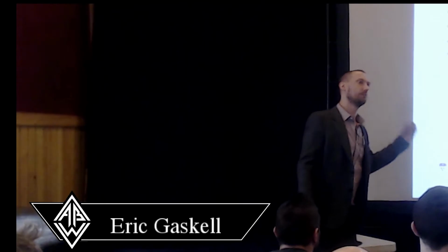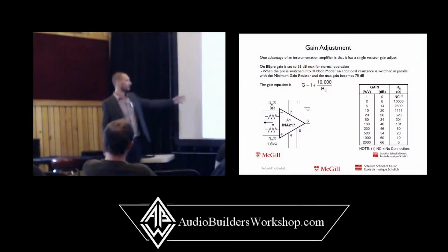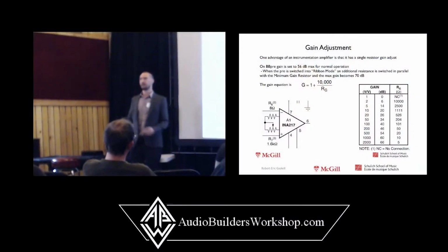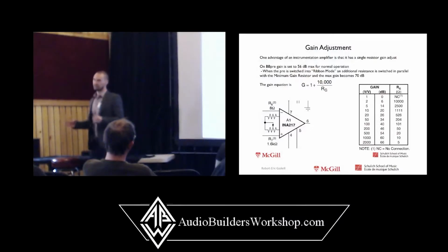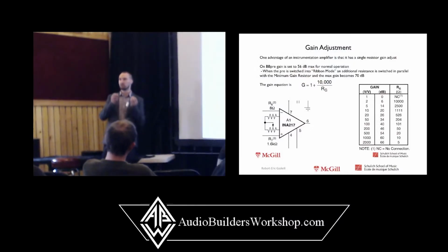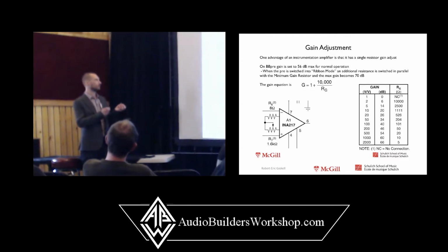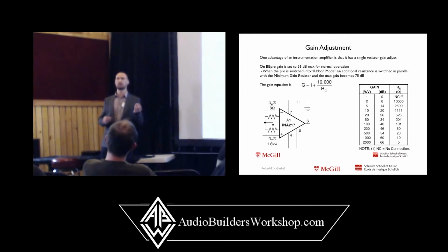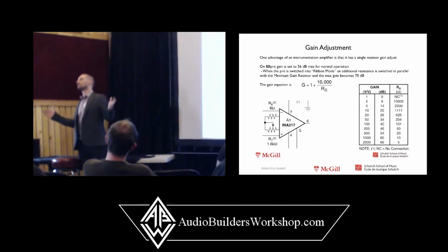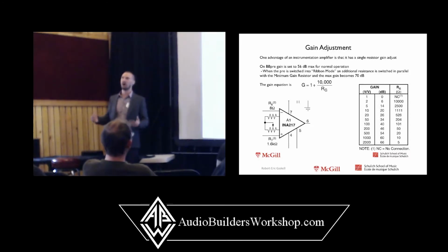And most of these circuits are designed in such a way that we have smaller value resistors for higher gains. So in the op amp, the transformer buffered op amp, the lower the value of the resistance in the feedback loop, the higher the gain. In this instrumentation amplifier, the lower the value of this resistor, the higher the gain. So actually at low gains, we have a large contributing factor to the noise of the circuit is the thermal noise of the resistor itself, but it becomes less and less of an influence as we increase the gain.